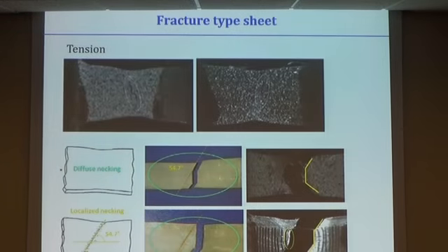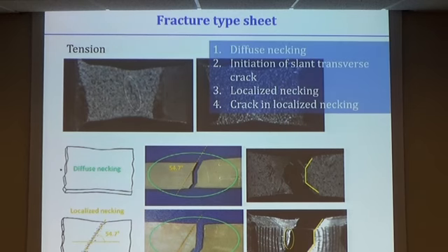Alright, some images of the high speed. So for the very small samples, for the sheet samples, we had a very, very beautiful, from an engineering point of view, fracture development, and we were able to capture the fracture process. So it was really textbook. What we observed was onset of diffuse necking, immediately followed by a crack in the middle.